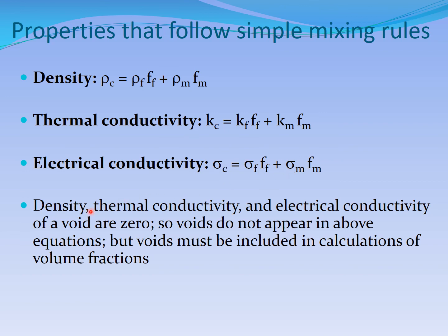So density, thermal conductivity, electrical conductivity of a void are 0. You see, density of a void is 0, so it does not matter. Conductivity of a void is 0, so it does not matter. Electrical conductivity too, so therefore it automatically goes away. It is not that we are neglecting it. In strength, it will be different. But in density, thermal conductivity, electrical conductivity, even though some voids are there, they don't matter.